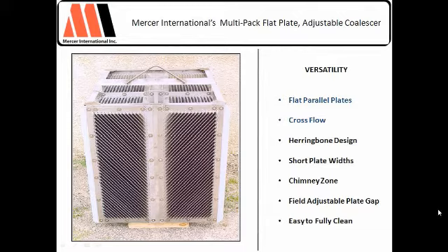So the first thing you're going to note is that this coalescer shown here is an entry area view. We're a little higher so you can see some depth. The flow is coming in this area right here. You'll notice flat plate design. It's a flat plate that goes all the way through the coalescer pack. Critical. And we're finding that this time-honored flat plate design is something we've come full circle on. This was the original design concept.